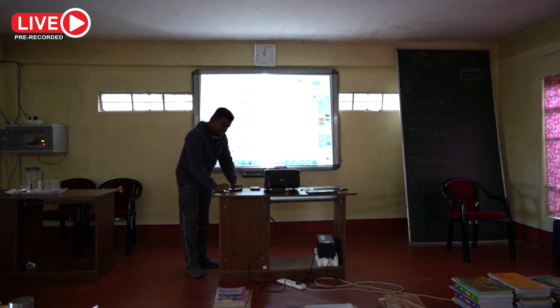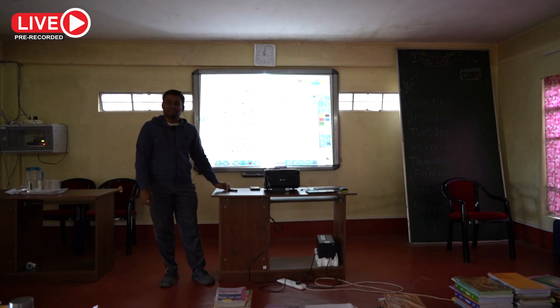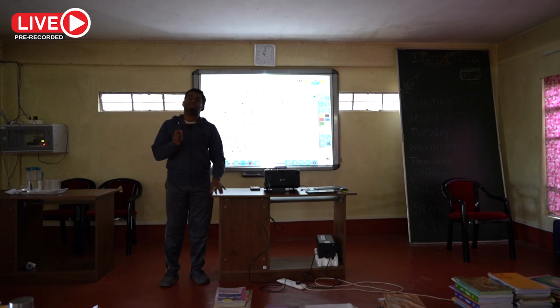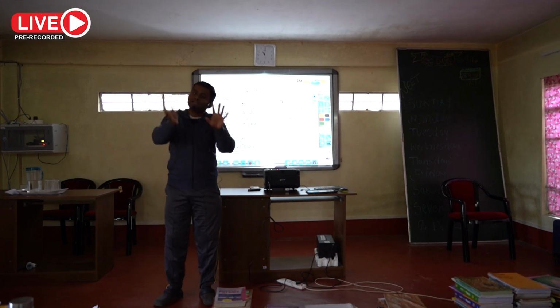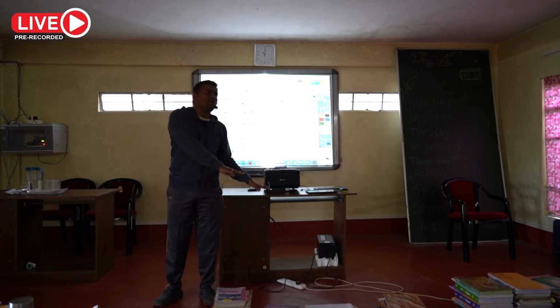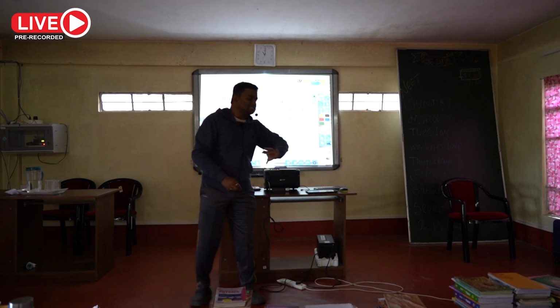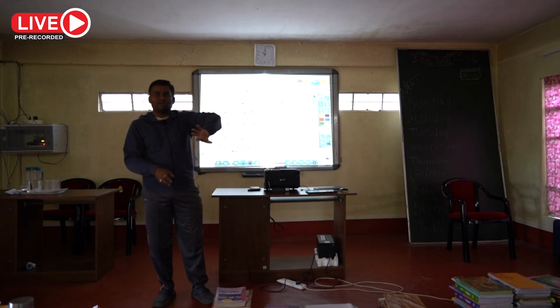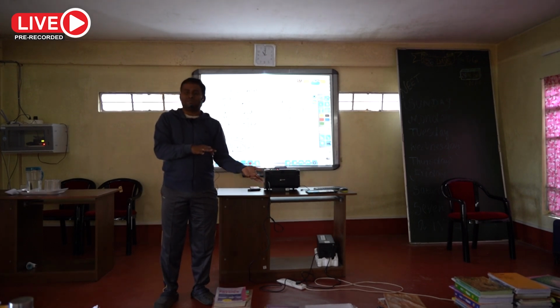Why? Because if you disturb it from this position, at every position of its rolling over the surface, the height of the center of mass above the ground will remain the same. So that configuration is called a neutral equilibrium. Neutral means, suppose a football: if you orient it in any condition and keep it on a horizontal floor, it will stay there. If you disturb it, will you say that after disturbing it this much, it will roll back and come back to the same configuration? No, the disturbed condition is also an equilibrium for it.